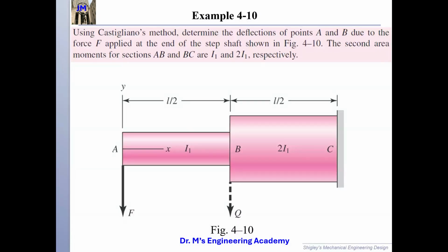Okay, if this is the case, I just draw it up here. I have a bending, this is F, and this is X. You bend it here, and then there must be an M_z here, and this M_z must balance your F. That means the sum of moments equals 0 lets us get M_z.